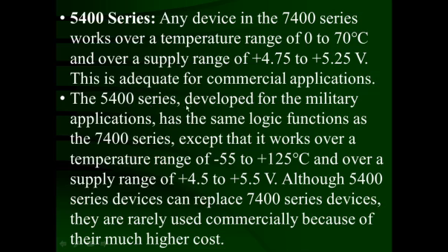The 5400 series developed for military applications has the same logic functions as the 7400 series, except that it works over a temperature range of minus 55 degrees Celsius to plus 125 degrees Celsius and over a supply voltage range of 4.5 volt to 5.5 volt. That means 5 volt plus or minus 0.5 volt tolerance is acceptable.